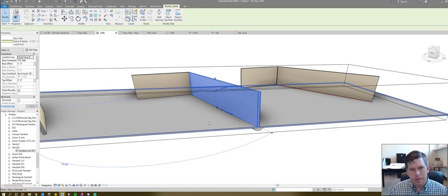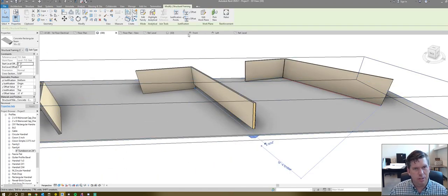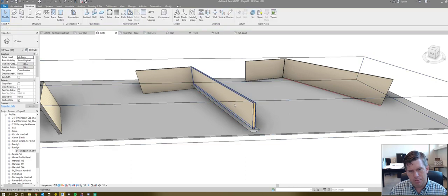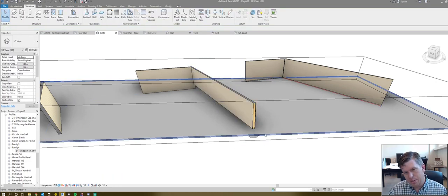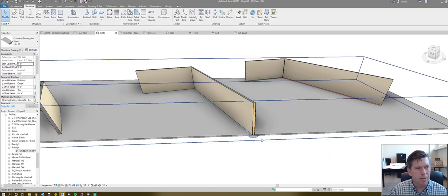Okay, some things to keep in mind for this are that if you change the offset of your wall, the beam does not go with it because it's based on the work plane of the slab. Now you might be able to pick the bottom of the wall. Yep, you can. After you create this, in order to keep that attached to the bottom of the wall in case that moves up and down, but that might not make sense because really it's based on where your slab is.